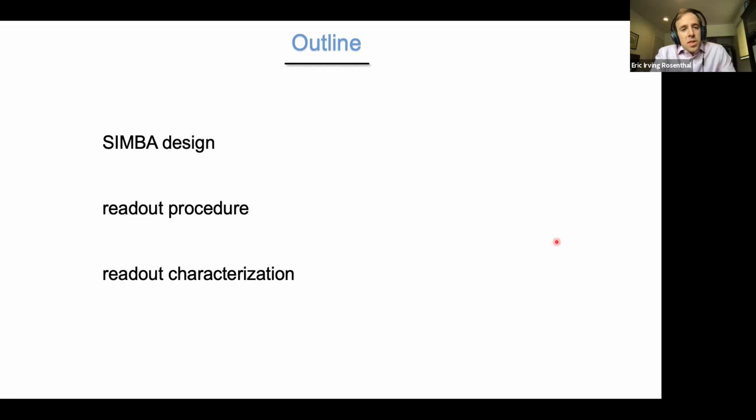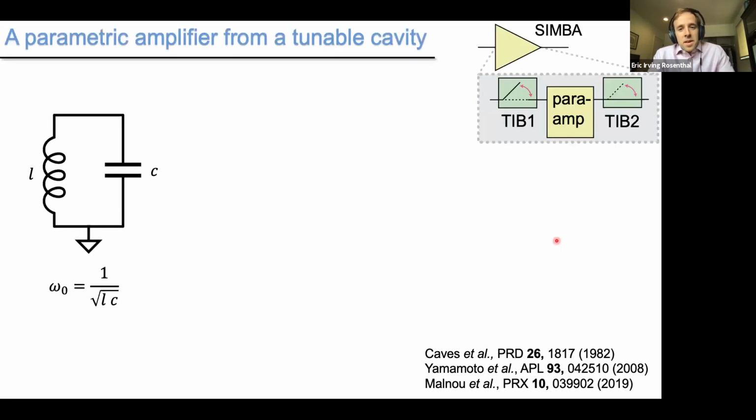Yeah, so I certainly think you could do that. I think in the shorter term, the HEMT and the circulators are very broadband devices. I can probably multiplex like 10 or 100 qubits per HEMT. So I can still remove most of my circulators because I'm removing the ones before my first amplifier. I think in the longer term, you could put switches before your HEMT instead of circulators, and time domain multiplex things. Yeah. Thanks.